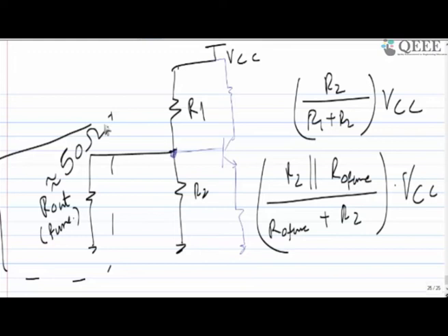So it gives the termination of 50 ohm to the ground, or there is a 50 ohm resistance between that particular BNC connector to the chassis. So if that is the case, and if I replace this value with 50 ohm, this one is also 50 ohm, right,